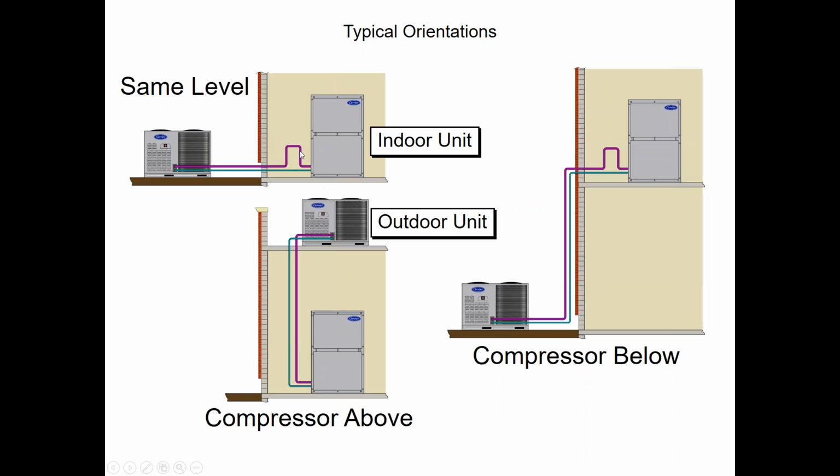And typically when you run inverted traps, you're going to take your suction equal to or slightly above the evaporator coil. All of that is to keep the refrigerant back here in the coil on the off cycle. If we don't have that trap, we could have the refrigerant, depending on migration from temperature, making its way back to the condenser, causing some flooded starts. But all of the equipment, and this goes for all manufacturers, everybody does what's called a flooded start test. So we know how much pipe we can have on the system in what arrangement or orientation without doing damage to the compressor. Flooded starts are something that everybody looks at as far as manufacturers go.